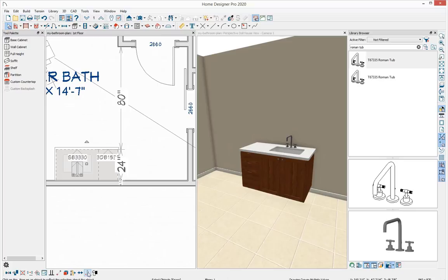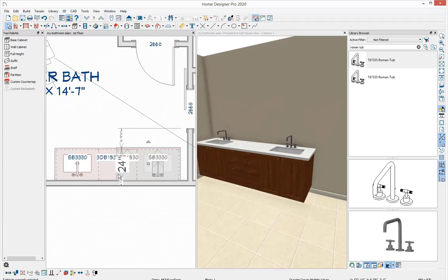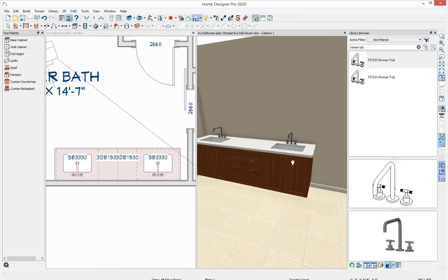So let's select this tool, and then we're going to bring our mouse cursor to the center of where we want our objects to be reflected. So I'm going to click in this area, and then you'll see that the copy that we just made is going to have a mirrored effect to the other side.